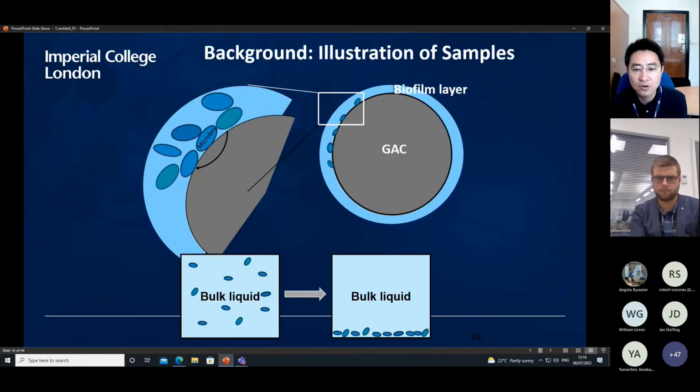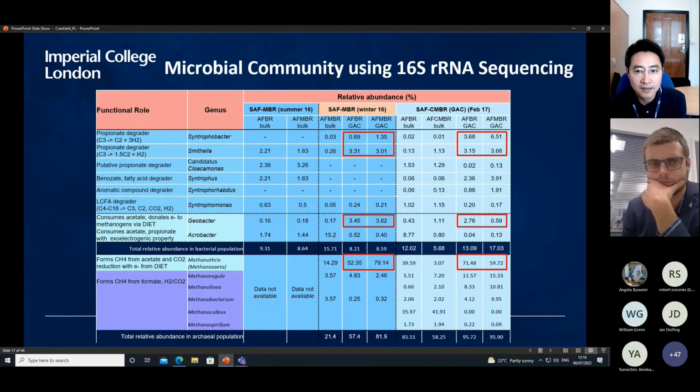So then the question is, because we control MLSS, most of the mixed liquor, or say bacteria, is actually in the GAC. Okay, about 90% of the biomass. We took samples to understand how much of the biomass is located there. So 80% to 90% is in the GAC. So we extracted DNA and RNA. And then we found out, you can see that.